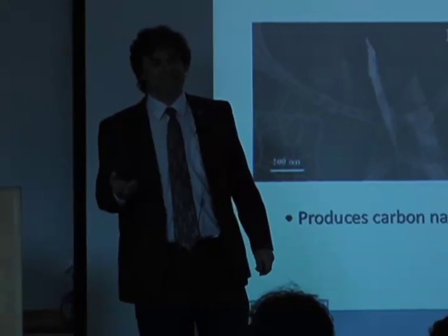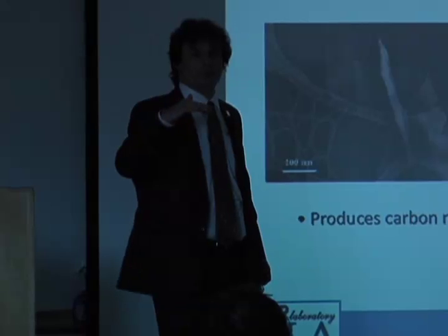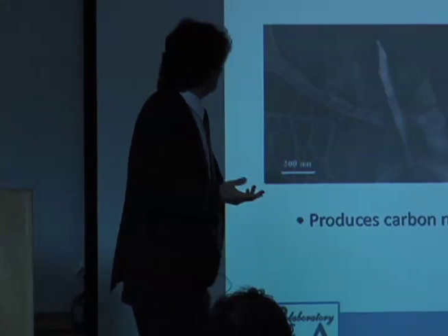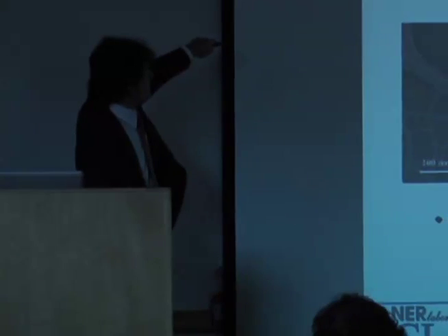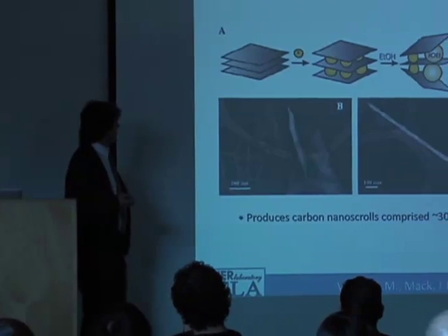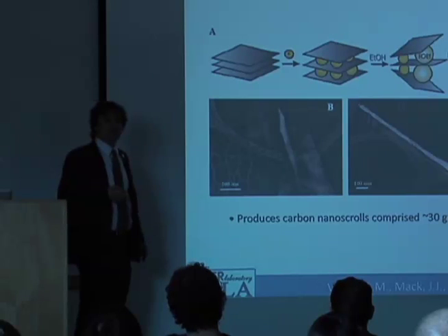And so he showed me these mechanical calculations he had done that showed a single layer carbon would be the best reinforcement for polymers because it would reinforce in 2 dimensions instead of 1. So then he's like, well, how would you do it? I said, well, you know, graphite's a layered compound, so I just heat in the presence of potassium. It's been known for many years that if you do this under inert atmosphere, you get a first-stage intercalation compound. The formula is KC8. It's bright gold.